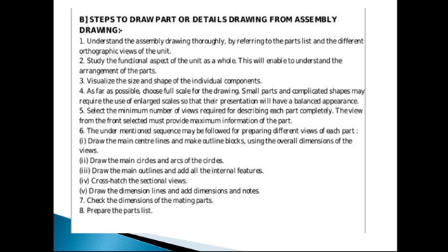So like this, just check number 1 and then check in your part list what is the name of that component, what is the material of that component, and how many times this component is used. Whether this component is used only a single time or whether this component is used 2 times. If the component is used 1 time, then check the location where it is used. If this component is used 2 times, then friends, check how many times this component is used and where the locations are.